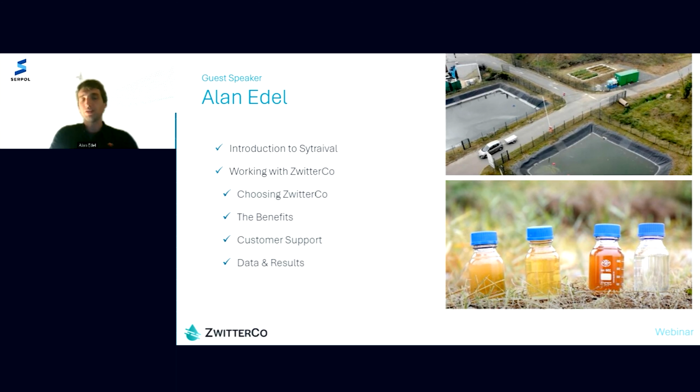First one, as always, was to reduce the treatment cost of the leachate. And the second one was to limit the consumption of drinking water that was used for residual on-site activities like truck washing or dust removal. It was a tender for a design, build, and operate contract. So Serpol was awarded this contract with a solution mainly based on a low pressure reverse osmosis, combined with some prefiltration, like Brett talked about, and a final disinfection by UV for reuse of the water on site.